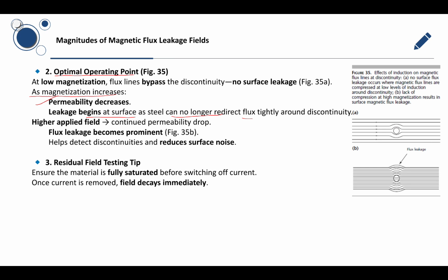With an even higher applied field, the permeability continues to drop and flux leakage becomes prominent. This not only helps detect discontinuities but also reduces surface noise, making the indications clearer.